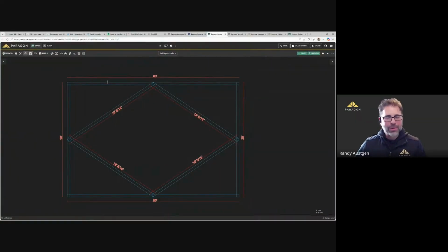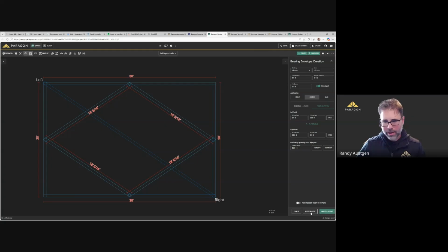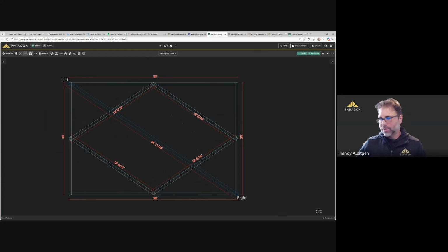All right, so for this next one, bear with me in this example, as I'm going to make a mess out of what we've got going on here. I'm going to center line this one because that's going to be fun. All right, and I'm just inserting and closing. So trimming versus picking points. This trim functionality, trim, extend, whatever you prefer, is going to be consistent for both layout mode and design mode.